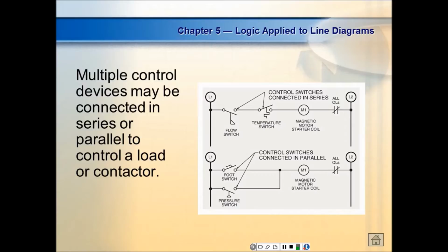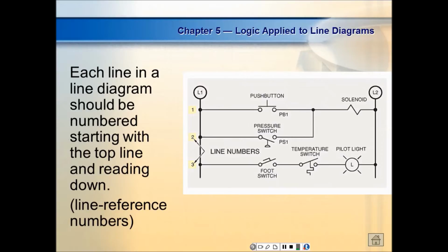We had a PLC here, one of the first ones that came out, one of the first fixed PLCs programmed in ANDs and ORs. So you'd have to say, I want to AND this contact with that contact, I want to OR it. And now we draw them. So line numbers. Every horizontal conductor has a line number, and we put the line numbers on the left of L1.